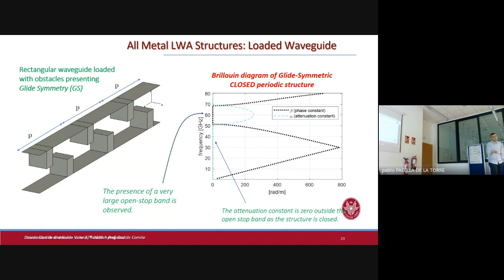Yeah. So this is nice because it opened possibilities, because I didn't have this in mind thinking about broadside direction with these liquid structures. The point is that people say, okay, cool, nice liquid antenna, because there is complex algebra behind, so you need a little bit of complex algebra. But in the end, if you have a dispersive antenna, the beam will change with the frequency. So if you have a wide band signal, you will get a percentage bandwidth there and the other percentage there, so the signal will be destroyed. You want to have fixed beam antennas.